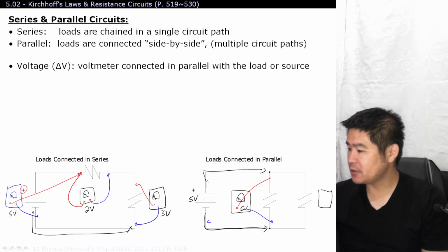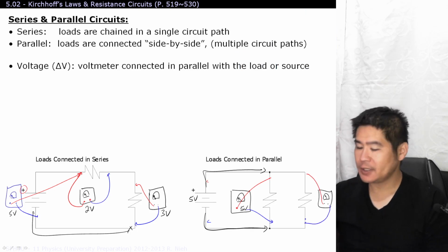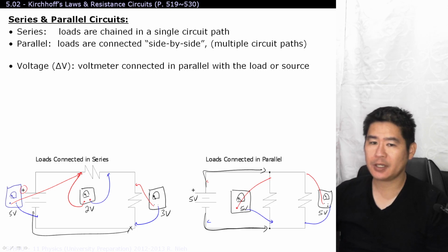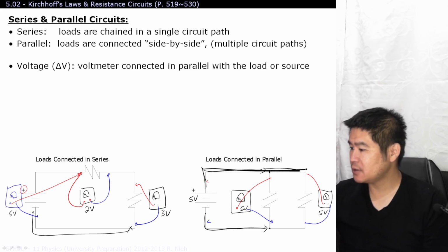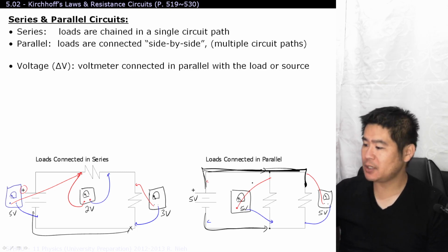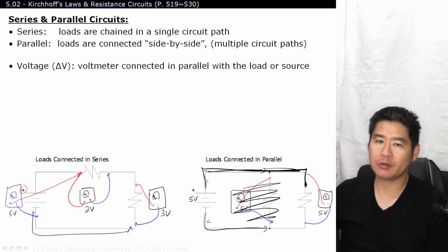And if you place another meter right over here, you connect the red closest to the positive and the darker one closest to the negative, even this last voltmeter will measure 5 volts, as you haven't gone through a resistor yet. All right, it's still going through the same dark lead. It hasn't gone through any resistor, meaning that if I unplug this guy over here, it wouldn't notice a difference. It would still register the same result.